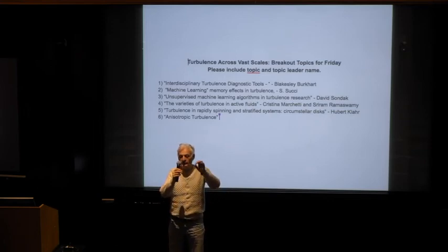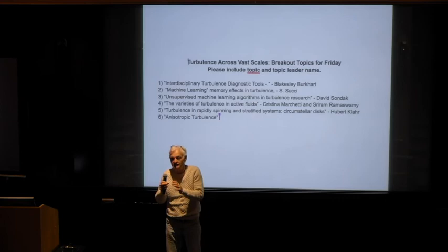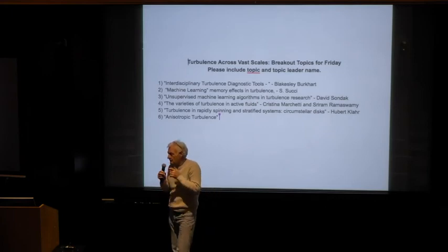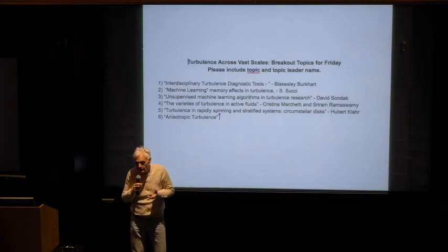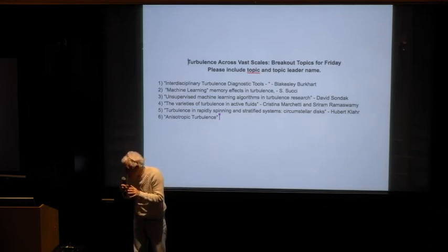Again, if you have a finite resolution in your simulation, as you always have, the largest eddy that you discard is basically equal to the smallest eddy that you keep, right? And these two eddies are bound to interact strongly, so there is no way their interaction can be described through the notion of eddy viscosity.